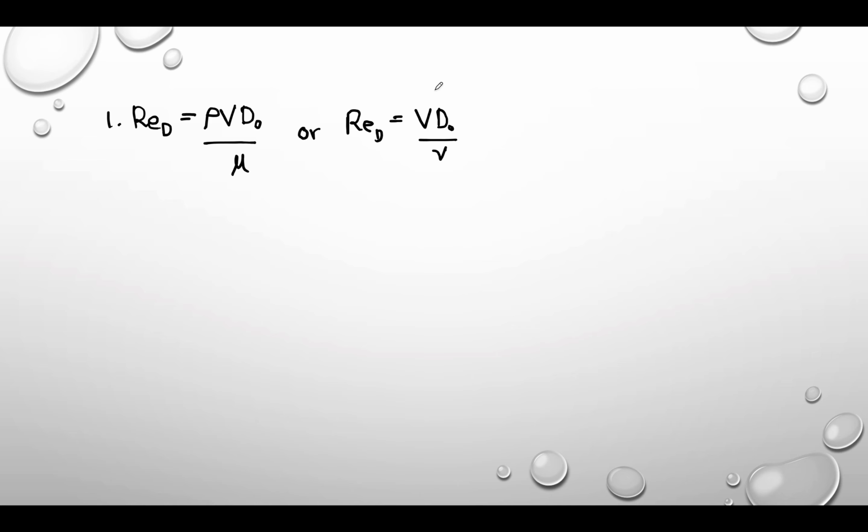We can use this equation, but actually in the tables we can find the value for the viscosity and density. But right now I will use the kinematic Reynolds number, where we have to use kinematic viscosity in the equation. So Reynolds number is equal to, so the velocity of the wind is 8 meters per second.